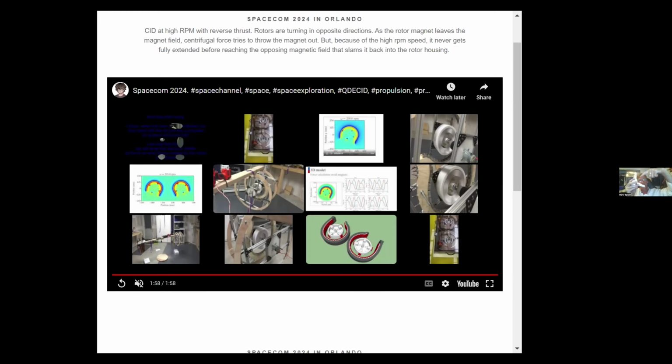As the rotor arm comes around, it wants to leave the orbit, but if you don't have that perfect little lip on it in order to bend that magnetic field around, the back of the magnet will reach around and grab the rotor magnet and slam it on the brakes. So I had to experiment and find the perfect little curve to allow it to break away. And then once I had that, I had to time the gap with whatever my RPM speed was and how hard my rotor arm comes out.